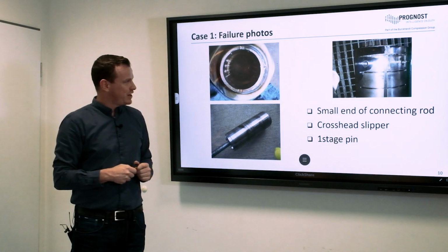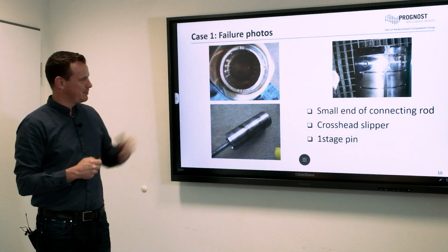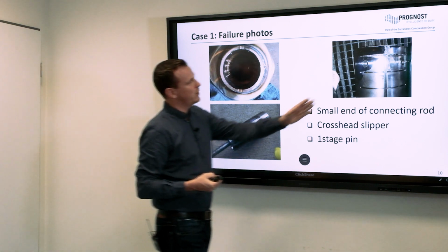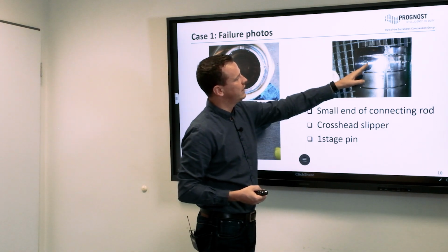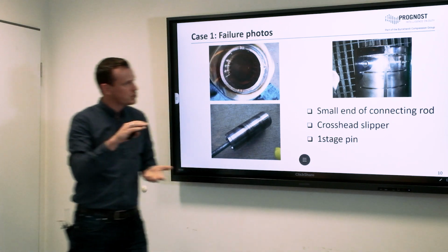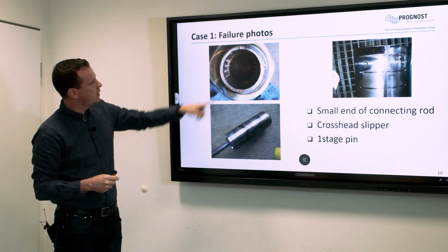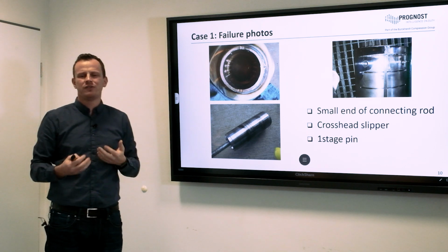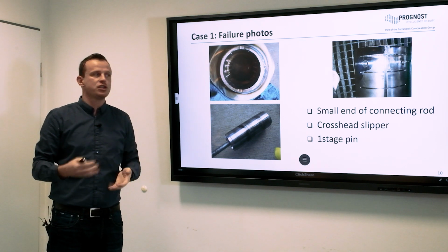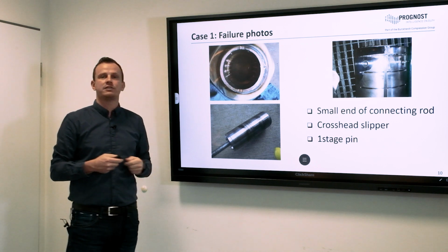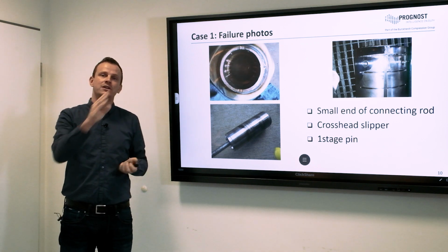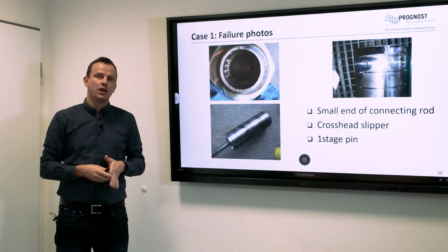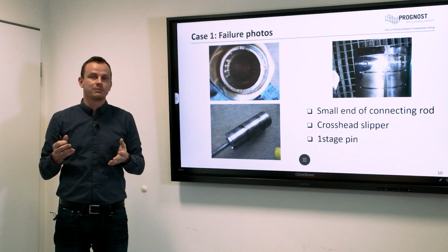If we check the pictures of that failure, the customer was so kind and sent us some photos. Maybe you see that in the best way here in the upper right photo, that we have the crosshead, which has already some wear. We are looking here at the small end connecting rod and as well at the pin, and all of these had already indications for a critical situation. So it was the right decision to stop based on the 0 to 7 kHz or even more kilohertz signal, which is recommended in many norms.